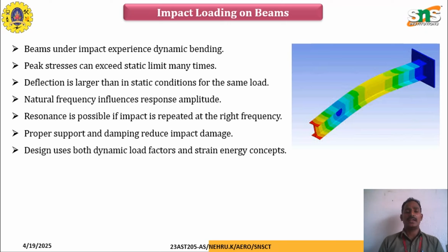We usually use this in aircraft wings or fuselage. Let us consider a beam under impact experiencing dynamic bending. Peak stress can exist, and the static limit may limit the time that can be measured. These deflections are large compared to the static condition for the same load, and the natural frequency influences the response amplitude of the beam. Proper support and loading conditions may reduce or dampen the impact damage. Designers should use both the dynamic load factor and the strain energy concept while designing beams like aircraft wings and fuselage.